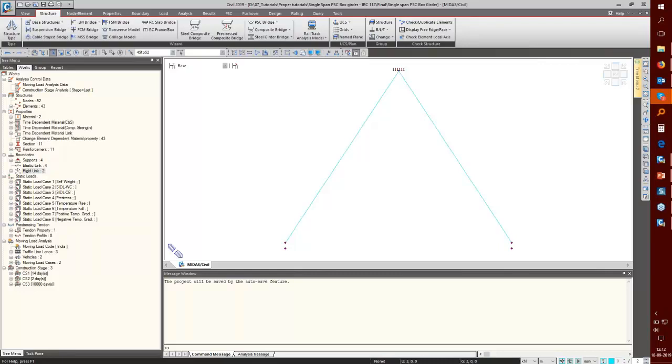Engineer Mohit is asking whether surface and pile springs are also added in the group, and if yes, whether this spring is activated at that stage. So what happens is, when do we want surface and pile spring boundary conditions to be activated? If we think about it, the soil would already be present, right? So its effect will start coming as soon as the pile is activated. So as soon as you have the pile activated in your model, your surface and pile springs should be activated in that stage, right, Engineer Mohit?